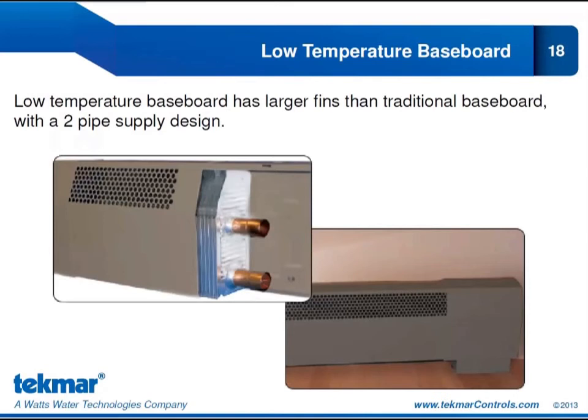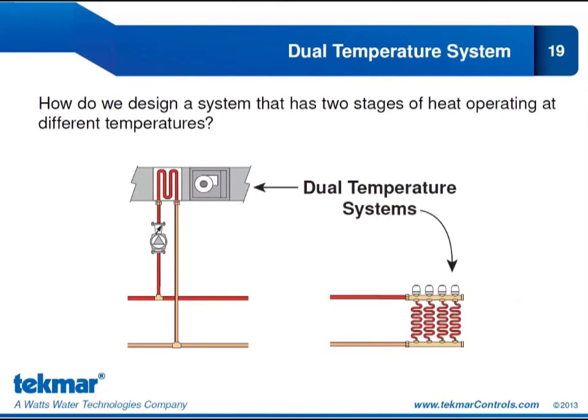So we just looked at some low temperature second stage heat terminals. Can we include these types of terminals on a design with a radiant installation at the same water temperature? Well, probably not. It isn't very good from a control point of view to have heat terminals that, even though they are all low temperature, still require different temperatures. So that's what we would call a dual temperature system.